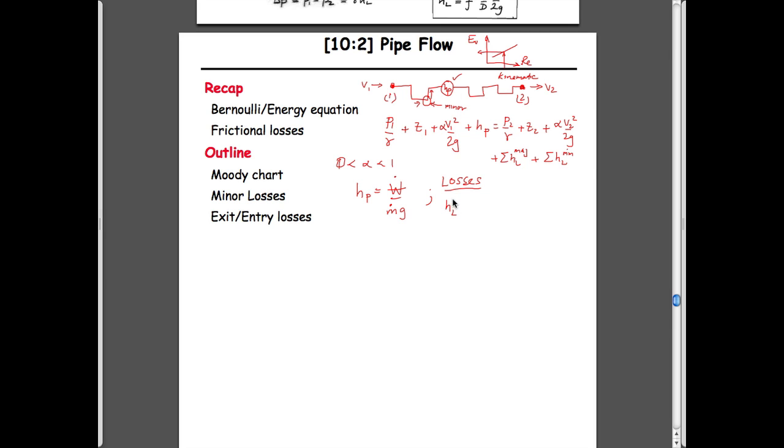And we've already actually seen them before. And so we know that minor losses are typically represented by some loss coefficient, I think we did this in conservation of momentum, multiplied by the velocity head term, v squared over 2g, which is defined by the velocity in the pipe, the scalar magnitude of velocity in the pipe as you go around this bend. We won't derive that, but we'll take that on trust. All it's saying is that we can scale the magnitude of this loss relative to the velocity head term.